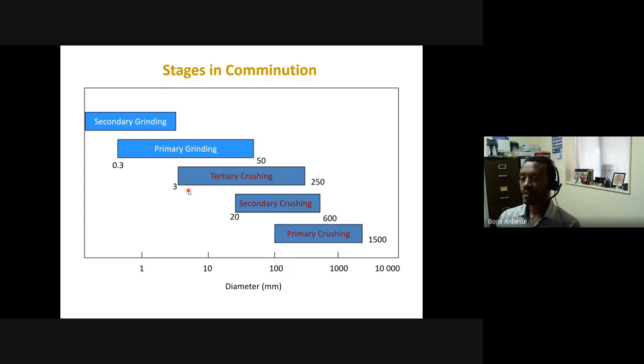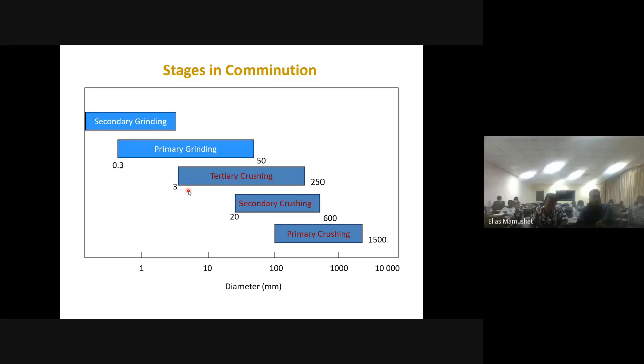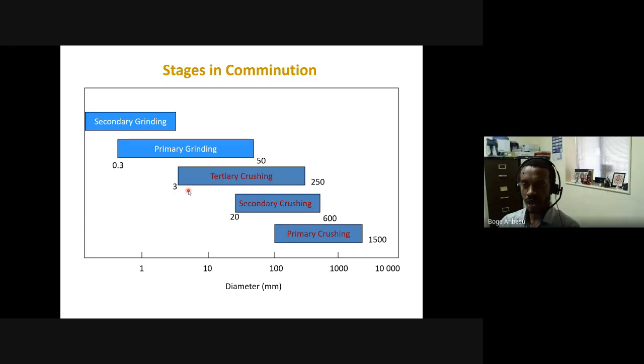So at the end of the day, it just comes down to the impact crusher applying very high force, shattering the rock, and producing lots of pieces. But the good thing is, if the rocks have been smashed with high impact and they're still intact, that means they don't have any residual fractures inside them. That's the main benefit of the impact crusher. And if they don't have cracks inside them, then they can be used for building blocks.